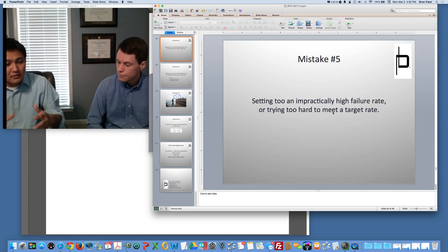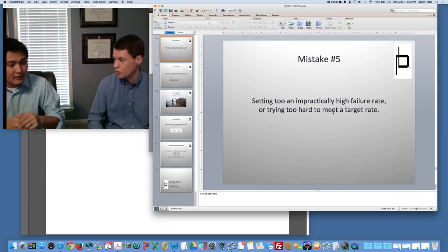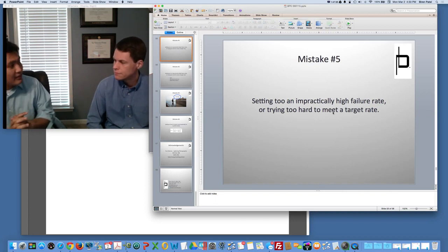Yes, you've reduced the chances of lightning entering your system to 1 in 500 years. But you've also made it very difficult because you have all these masts and wires around. It's going to be hard to navigate that substation, and hard for equipment to go in and out. Now you've got all these obstructions in place. What if you need to change out a transformer? You've got a mast right next to it. It's going to make a lot of things more expensive.